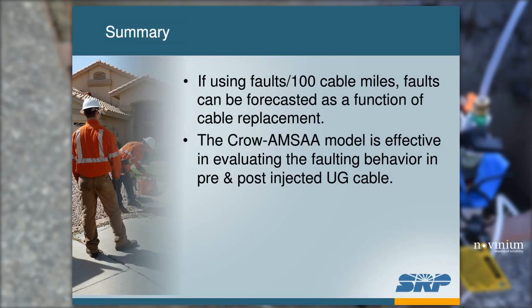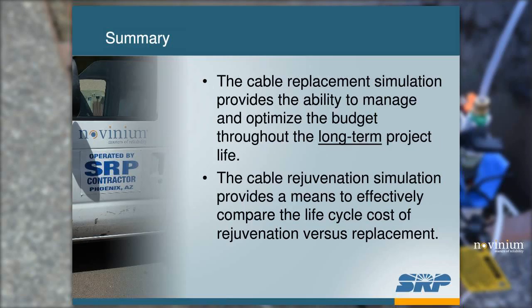Crow-AMSAA model, again, as you saw with our injected cable, it's great at evaluating the faulting behavior before and after injection. The really nice thing about it is it gives you that long-range view, and it allows you to manage over the long range and optimize your cable replacement over that long range, and your cable injection rejuvenation likewise.